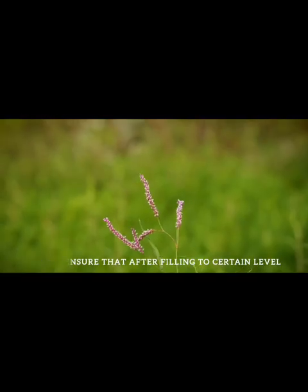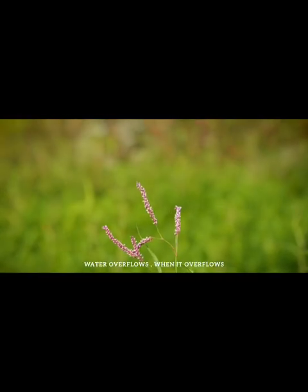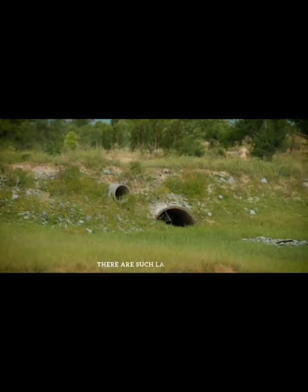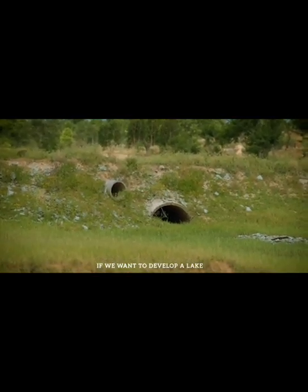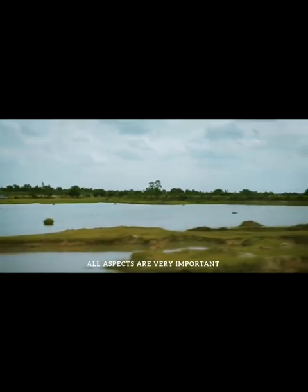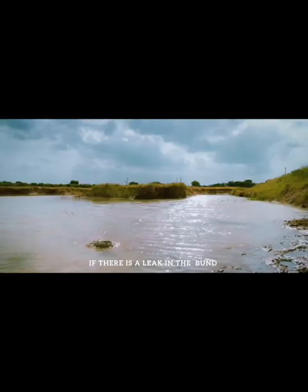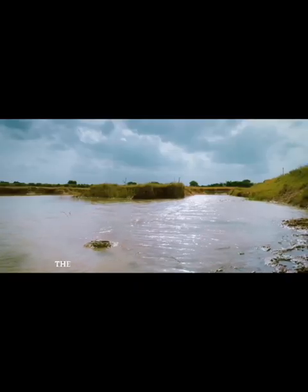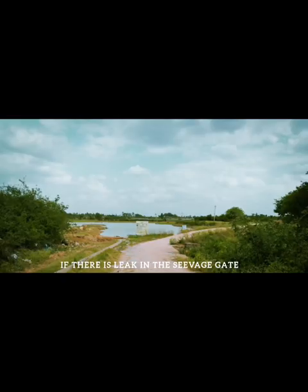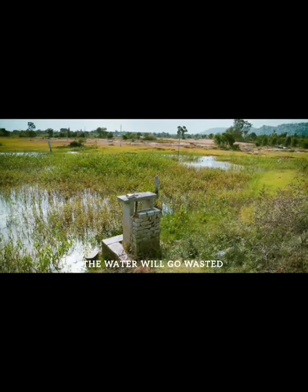So we ensure that after filling to a certain level, water overflows. When it overflows, the water should not be wasted. It should flow into another lake. There are such lakes in series. If we want to develop a lake, all aspects are very important. If there is a leak in the bund, the water will not get stored in the lake. If there is a leak in the sluice gate, the water will go wasted.